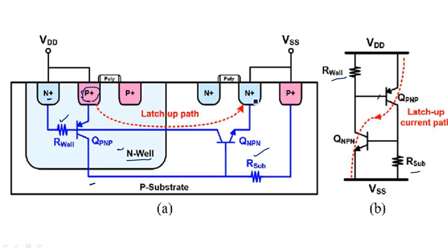So now when you redraw the entire circuit, it will appear like this, with a common closed loop where the two transistors and two resistors are connected in different directions. So because of this, what happens? Because of the existence of these unnecessary virtual components, the original behavior of the CMOS inverter will vary. The original CMOS inverter operation will be varied. That means, how to avoid this? Okay, we are saying that it is a problem. What is the solution or remedy for this one?